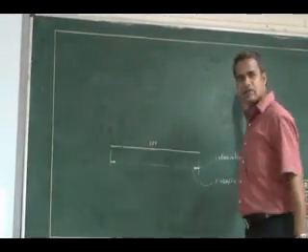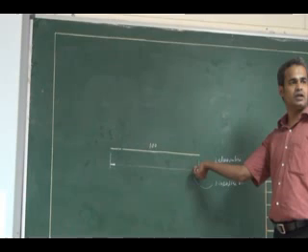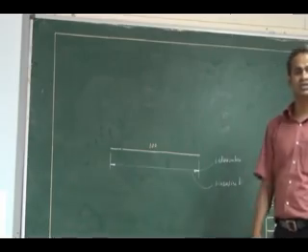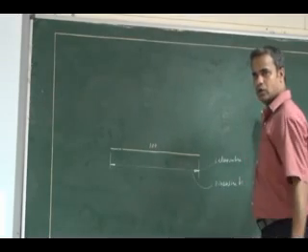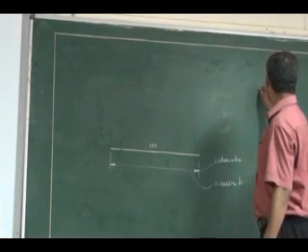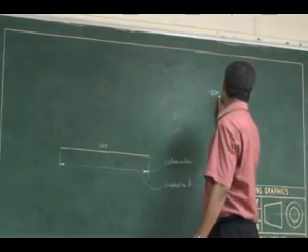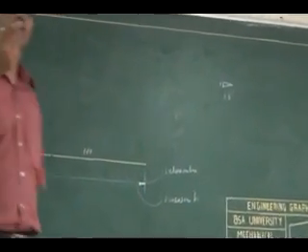The arrowhead has a ratio. If the width, the height of the arrowhead, is 1 unit, the length of the arrowhead should be 3 units. Suppose in your drawing you are using a height of 1 mm, the length of the arrowhead should be 3 mm. So try to draw the arrowhead as small as possible, in a 1:3 ratio. Make a note, quickly, in parallel.